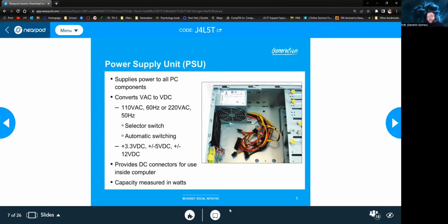It might be that it's on. It might be that someone didn't put it on. But the point of that lab is to remind you that switch is there. So the fact that it's not turning on might be just because that's a switch to the power supply. So it might be that switch is off in the back. The point of the lab is to teach you that power supplies may have that power button in the back. So even if you're pressing power on the front panel, because the power switch of the power supply is off, there's no power flowing in.